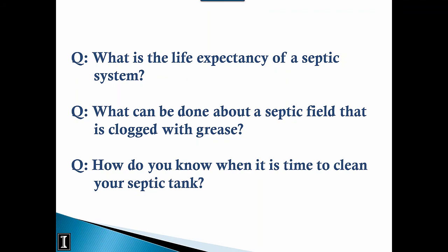Another thing would be, when you have your pumper come, whatever your routine time would be, to just ask them, could I have waited another year or two? And if nothing's changed, the situation is the same flow, same number of people living in the home, then maybe you can extend it the next time to 2 to 3 years and just kind of see how it works from there.